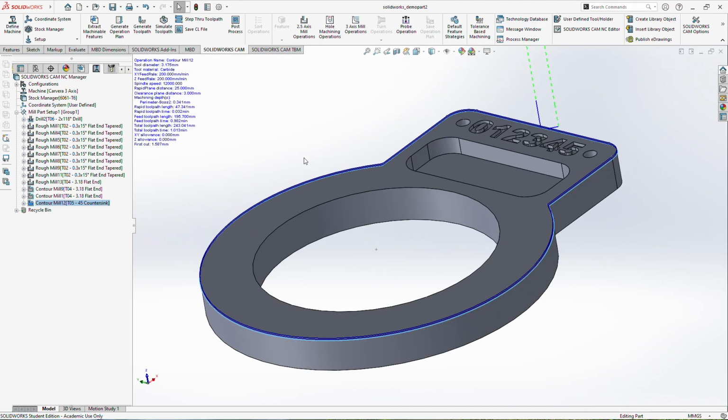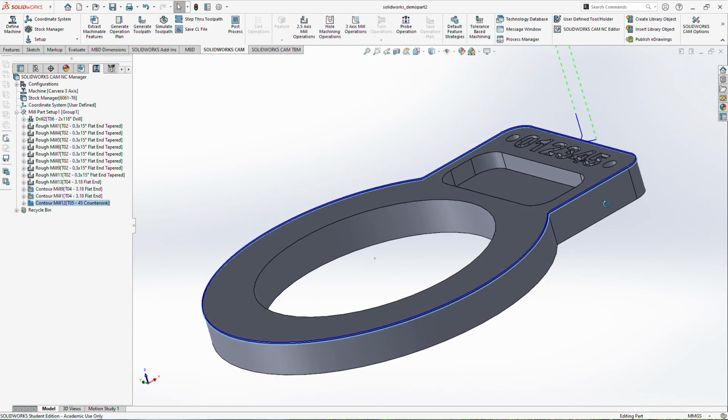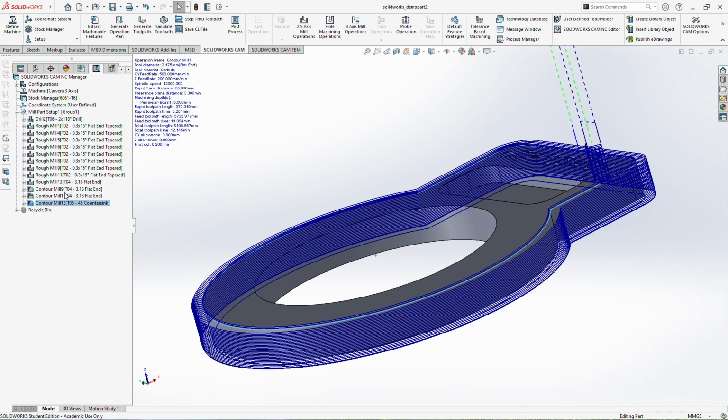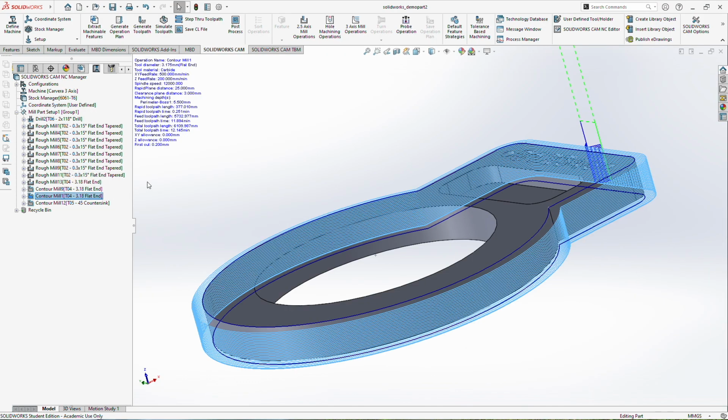Now, the only other thing I might want to change about this project is I have my chamfer happen after I do my contour cut, which is important. That's something that I need to do because, of course, I don't want to do a chamfer without the edge being cut. But because I'm only holding this part using double-sided tape, I don't actually want my countersink to push this loose. So what I actually want to do is start my contour cut, then do my countersink, and do a tool change, and then finish my contour cut.